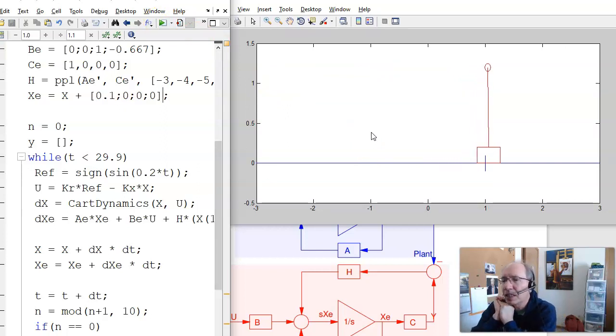And C, initially, this is a little bit different. Fairly quickly, it starts to track. Once the observer error is driven to 0, it remains small. It's not exactly 0 because the plant has dynamics the observer doesn't take into account, like the Coriolis forces, the nonlinear terms. But the feedback says whatever those errors or disturbances are, those effects are quickly driven to 0.